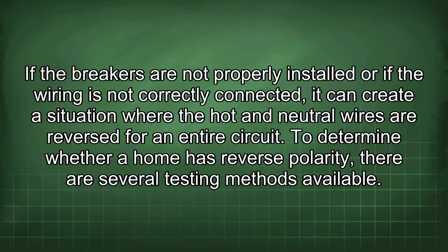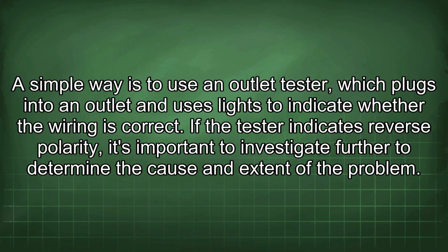To determine whether a home has reverse polarity, there are several testing methods available. A simple way is to use an outlet tester, which plugs into an outlet and uses lights to indicate whether the wiring is correct. If the tester indicates reverse polarity, it's important to investigate further to determine the cause and